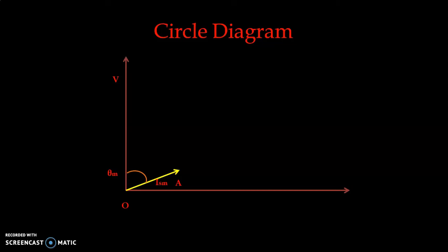In the previous lecture we have seen how the starting torque can be derived, the equation for the starting torque. So if we select the number of turns, then the ratio K can be derived, and XLA, that is the reactance of the starting winding, can also be derived. So based on this, the only variable parameter is the resistance of the starting winding, and the resistance of the starting winding will decide the total stator resistance.